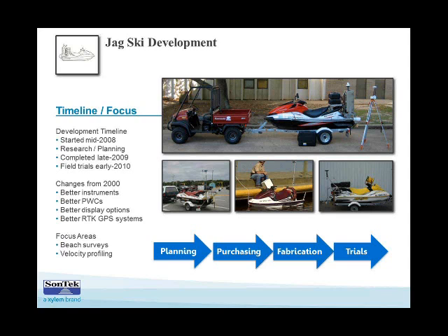So here I'm showing a color map time series that I've chopped down and cropped so you can see detail of the vertical beam signal to noise ratio. So it's high at the surface and then high again at the bottom, picking up the reflections at the bottom. And there are all sorts of color map time series that you can make from velocity and depth and signal to noise ratio and all sorts of different things. So a lot of good capabilities within the software itself.